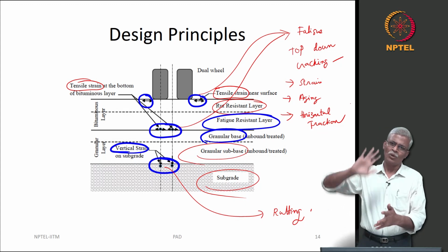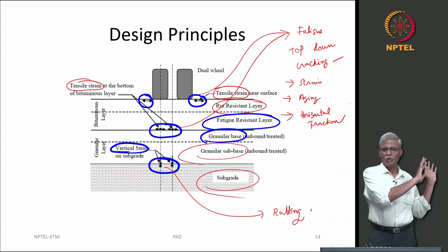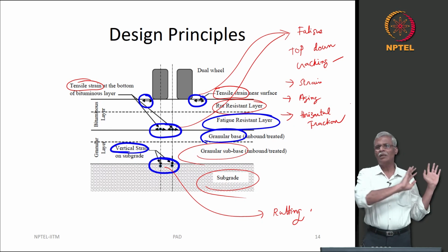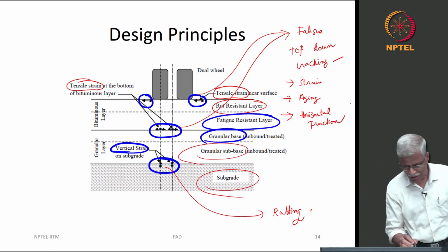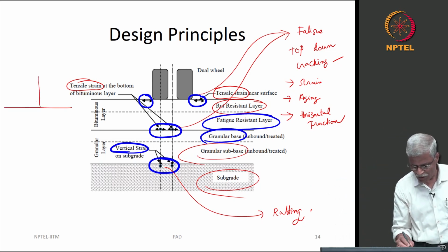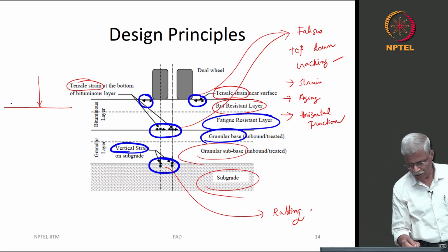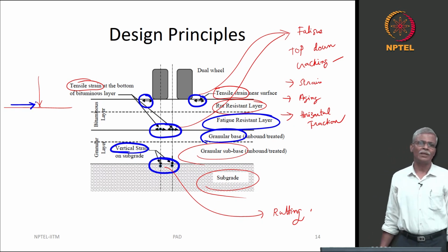So, what do you do? You press the brake. So, when you do that, what will happen? Momentarily there is going to be a load transfer from the rear to the front and it goes back. So, if you try to resolve the forces, there are going to be forces in the vertical direction, there are also forces in the horizontal direction.